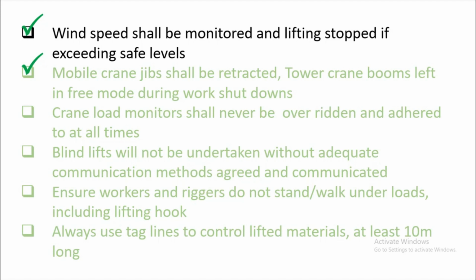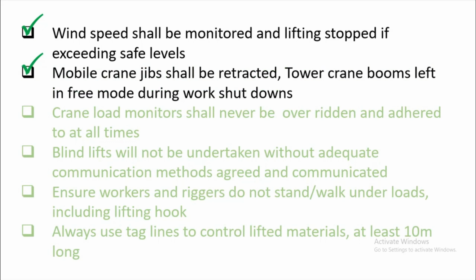So when you are doing your lifting assessment, you need to include the wind speed at that time, and monitor the wind speed from time to time while the work is in progress. Mobile crane jib shall be retracted. Tower crane booms left in free mode during work shutdowns.